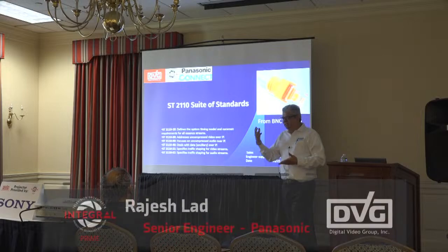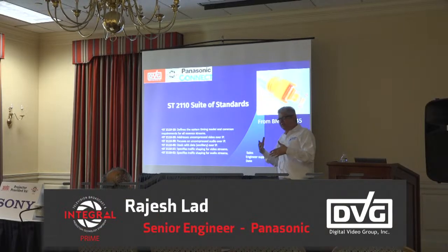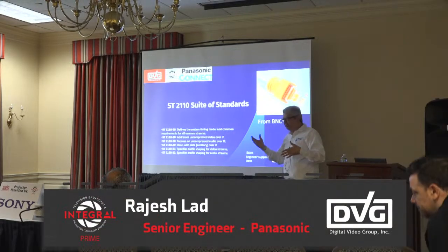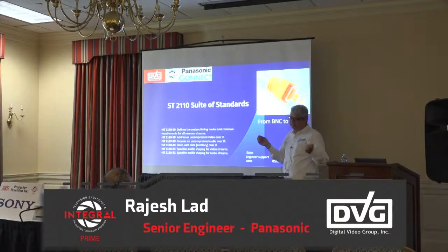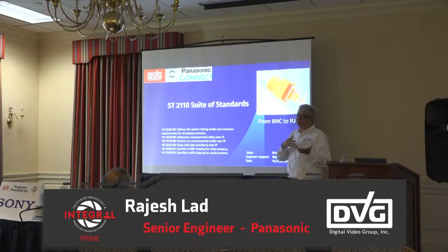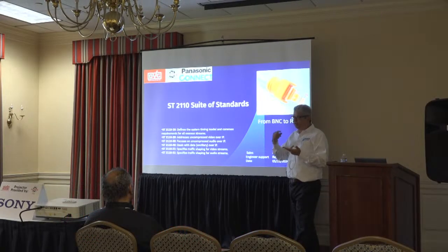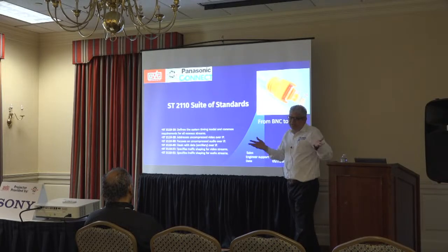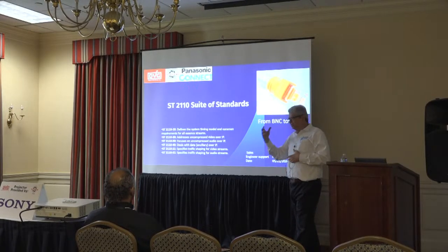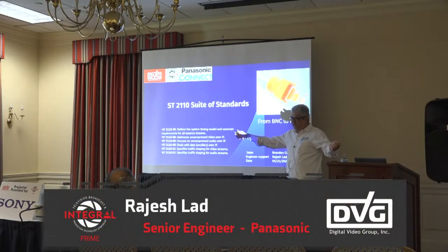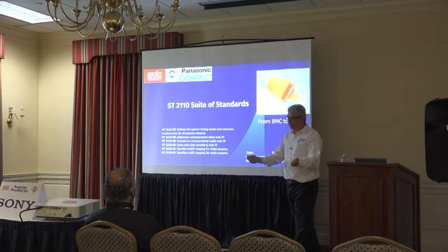Then they added in the SDI video all the 3G and 4G, 6G and 12G and everything. And SDI video has transportation done for the audio, for the video, for metadata, everything you can put in. So it was pretty good. It lasted. The only problem is the length. As you go from 3G to 6G to 12G, the length of the cable started shrinking.